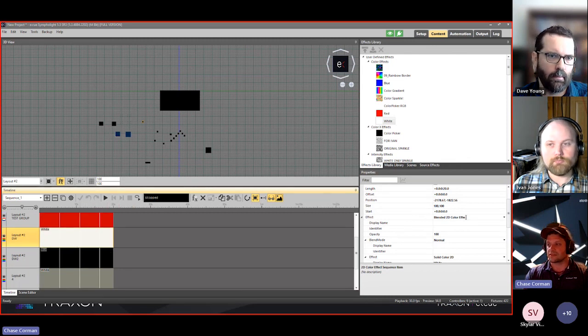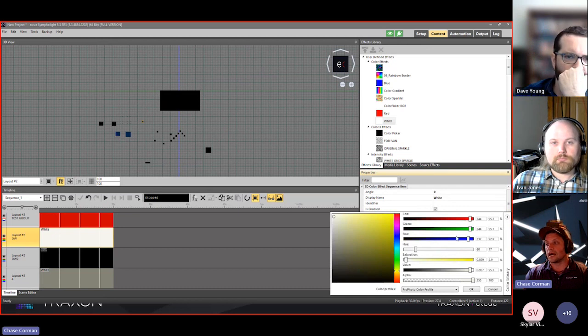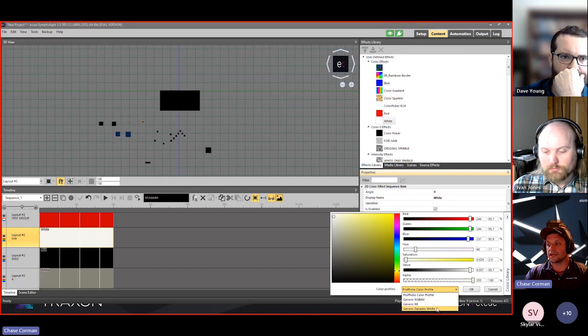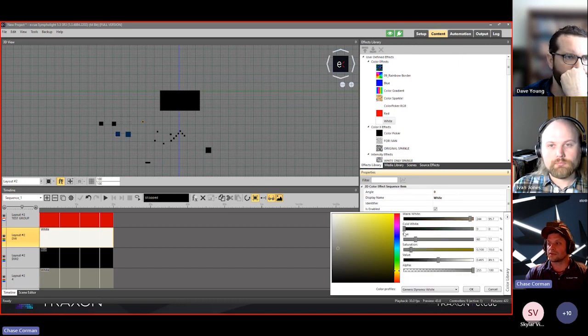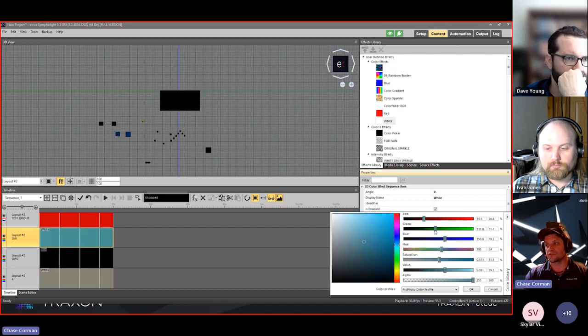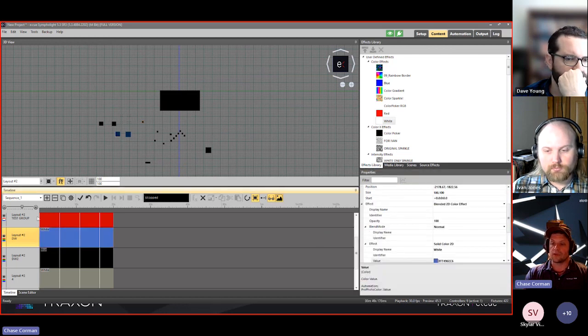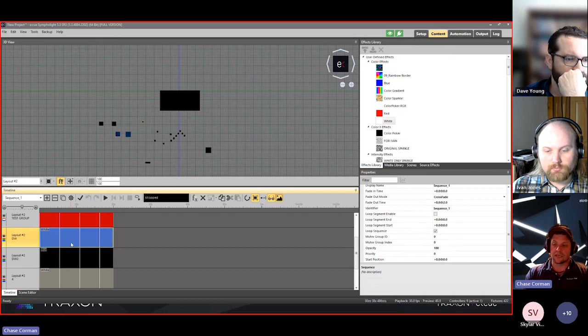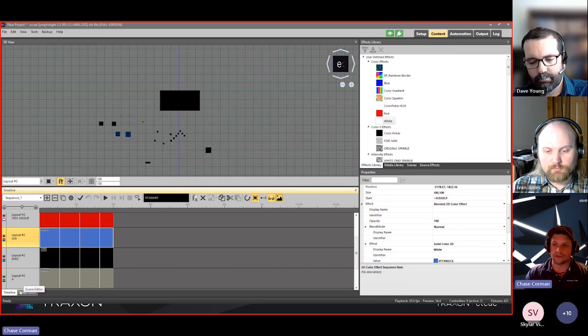But if you select your effect over here and slide down to where your color would be, there are different color profiles that you'll see here. If you click on this drop down, you can get generic dynamic white, which will give you some options for warm white and cool white, specifically those named faders. So again, if you're using 3-channel, my best recommendation would be to use that 3-channel fixture, and then use probably the Pro Photo Color, and just assume that your red is first, green is second, and your blue is your third white. You can also see that in the scene editor too, and Ivan can show you some more about that a little bit later today.